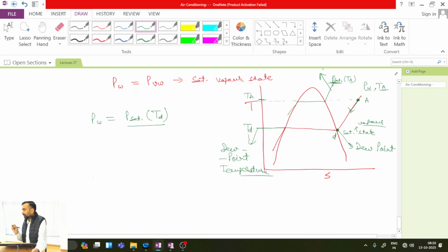So in terms of enthalpy, because moist air contains dry air and water vapor. For dry air, already in the previous lecture I told you that enthalpy will be a sole function of temperature, considering the reference state at 0 degree Celsius. It means at 0 degree Celsius, if I assume H is equal to 0 kilojoule per kg, then I can simply write HA as 1.005, which is the Cp value, times T. Is this one clear? So for dry air, I have already written this in the previous lecture.